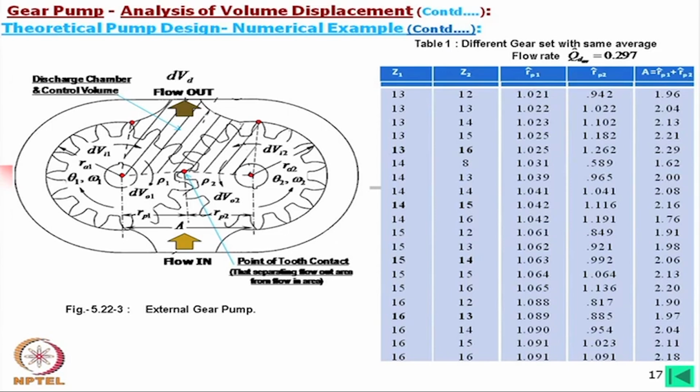The only problem is that we have to analyze the contact, so that if the contact tries to approach beyond the involute, then there will be some problem. Again, if a cutter is designed properly, that is the pinion cutter, we are considering the straight tooth, or in mass production definitely a hob cutter, then it is also possible that with 12 teeth uncorrected, the root fillet is not